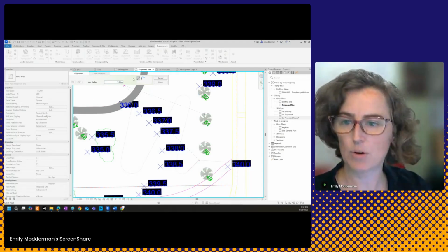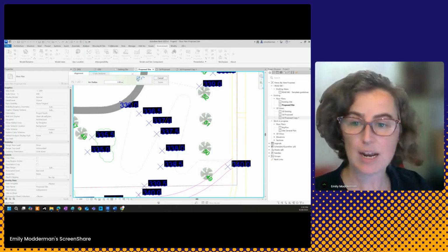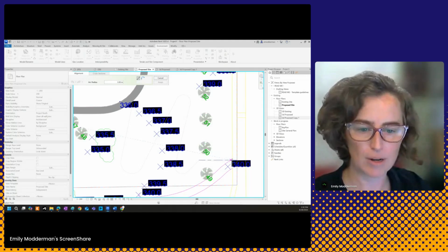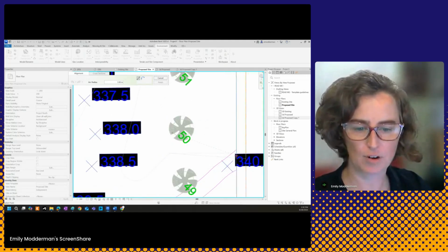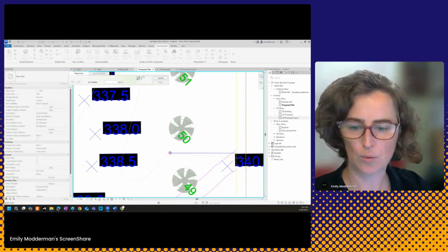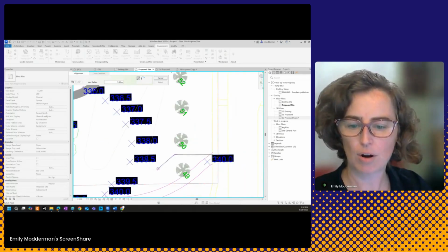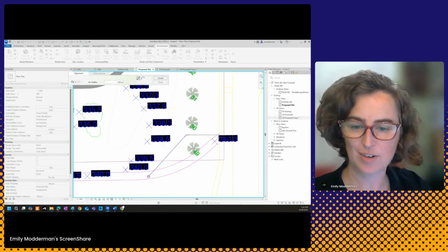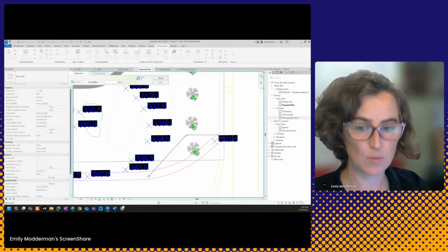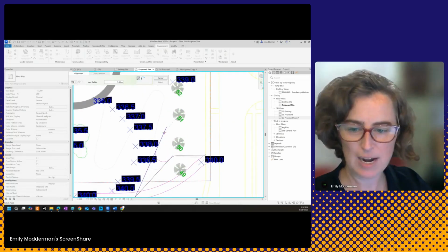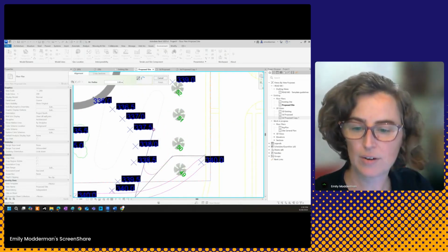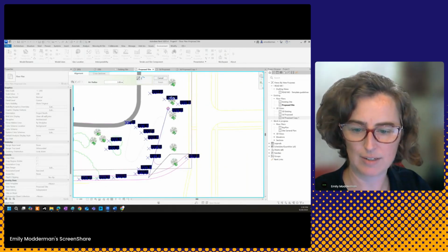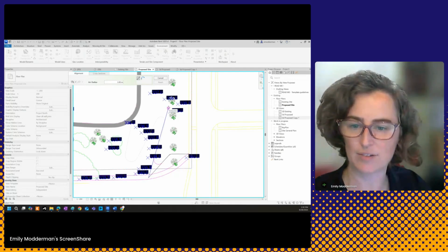All right. Now I'm going to start drawing. As of right now, we have a draw and an arc tool. Just wait. I think there's going to be some more tools coming in, and I'm going to start my pathway. It will automatically radius your line work. Sometimes we have to adjust for that though, right? I've got to make a point and it will radius it for me. So you can see there it's got my radius. Now I can adjust all this information as I go.